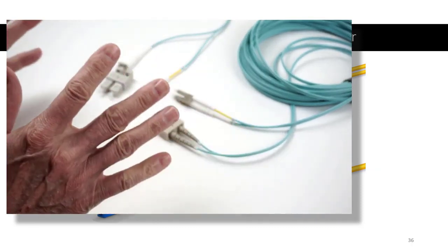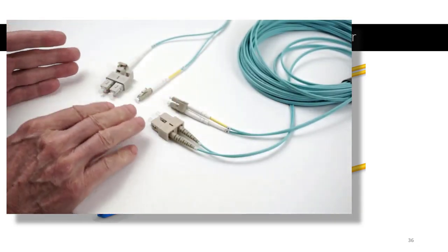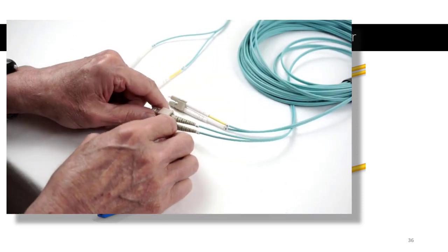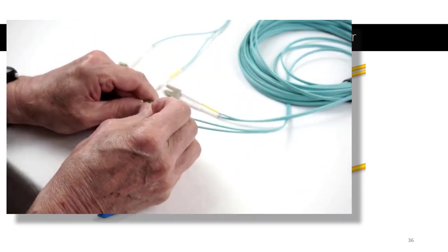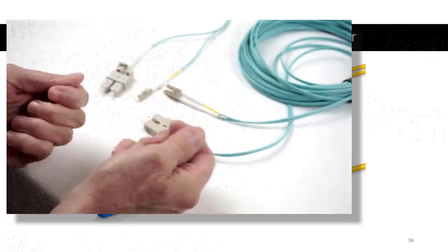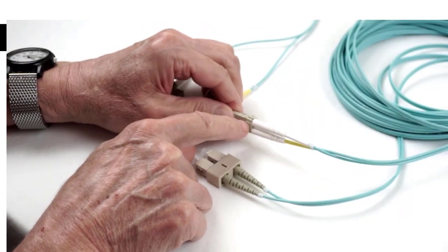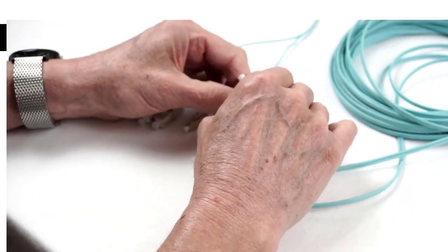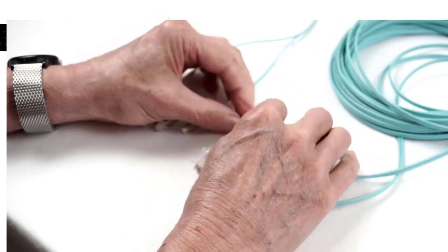Now you can break them apart. Most manufacturers will allow you to gently pull these apart. You can usually take a gentle screwdriver and pop these apart so that you can use them independent of this duplex connector or this duplex collar. This LC connector has a small break in the plastic collar, and if you're real gentle with stretching the plastic, you can pop these out of their collar and use them independently.